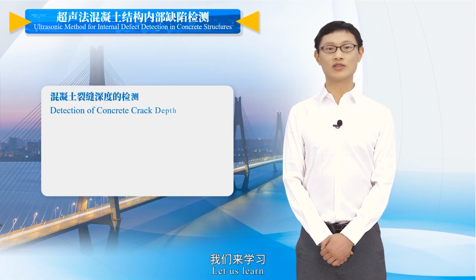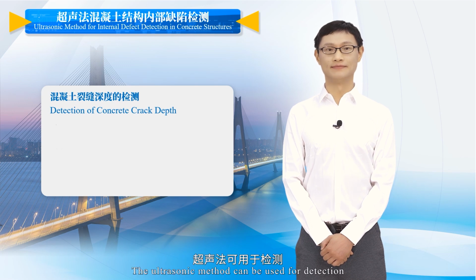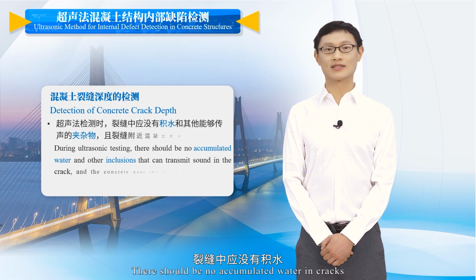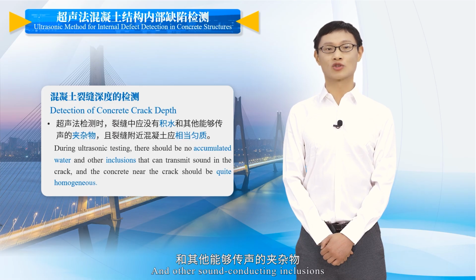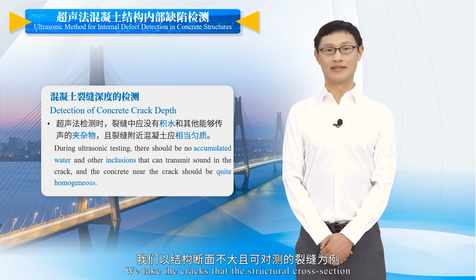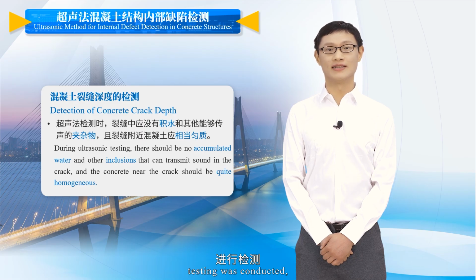Next, let us learn the detection of concrete crack depth. The ultrasonic method can be used to detect the depth of concrete cracks. When testing, there should be no accumulated water in the cracks and no other sound-conducting inclusions, and the concrete near the crack should be fairly homogeneous. In this lesson, we take as an example cracks where the structural cross-section is not large and parallel testing can be used. Testing was conducted.